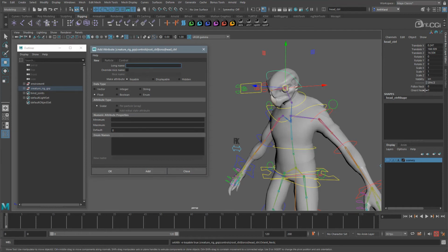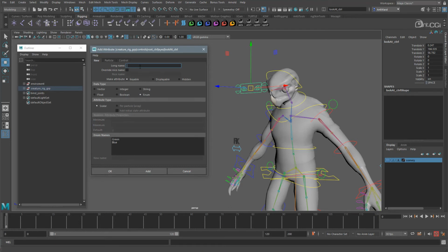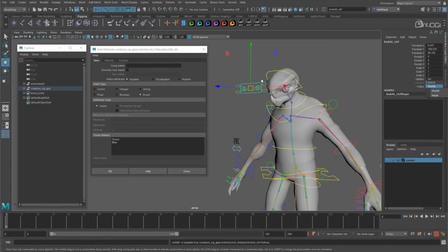These will control how the head moves, so the animator can essentially keep the head level as the body moves. OK, onto the eyes now. And we are back to using an enum. Set this to World and then Head. So we want the eyes to either remain in world space or follow as the head moves.